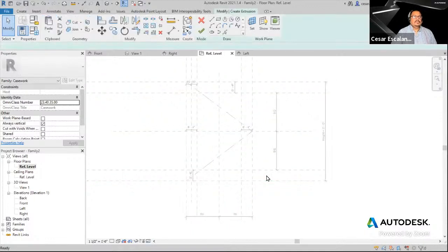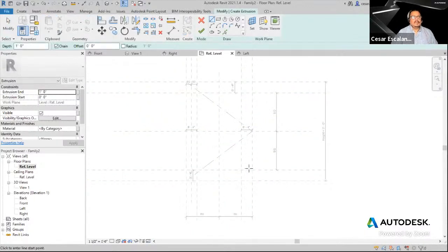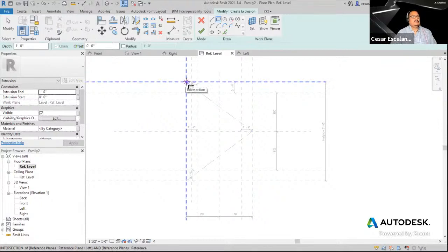So you go to the extrusion, you are in the sketch mode. All you can do is create a sketch line. The easy way to do this is using rectangles. So switch to the rectangle tool in the draw tools. And again, I'm going to snap to the intersection. And notice how this is telling me endpoints. I want to avoid snapping to solid geometry, and to force it to snap to intersections, type on the fly SI, snap intersection.